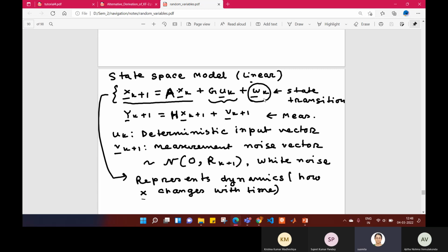Although this is not the right way to implement the Kalman filter, because if the process noise is 0, if you pay attention to the Kalman gain that you will calculate with each measurement, you will see that it is decreasing. So Kalman gain decreasing means the filter is actually not giving much importance to the measurements. It is relying on the state transition model more, because you have said that the process noise is not there. So this is not how the Kalman filter should be implemented, but for that problem we need to do that because there is no process noise.